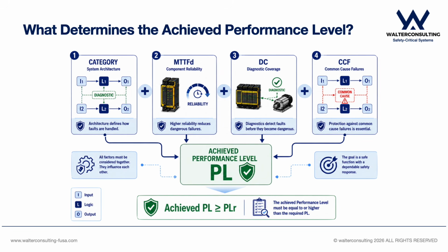The third factor is diagnostic coverage, abbreviated as DC. Diagnostic coverage describes how effectively the system detects dangerous failures. This is particularly important in architectures that use monitoring or redundancy, because a fault that remains undetected may influence the safety capability of the system over time.